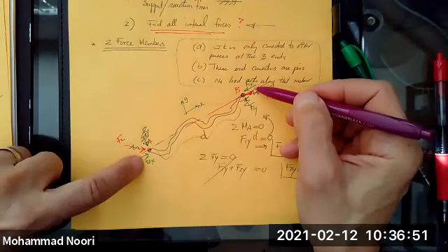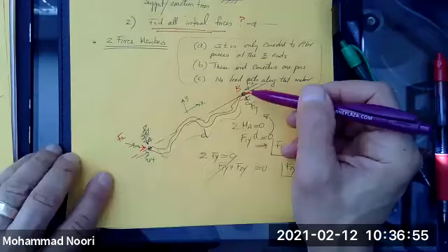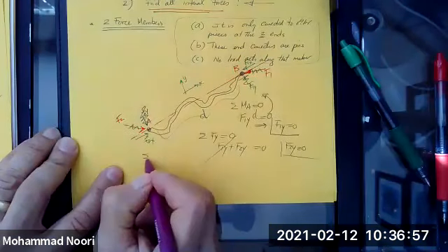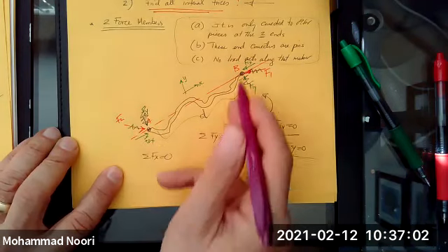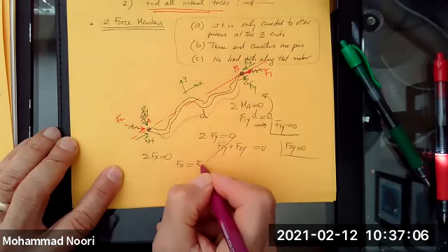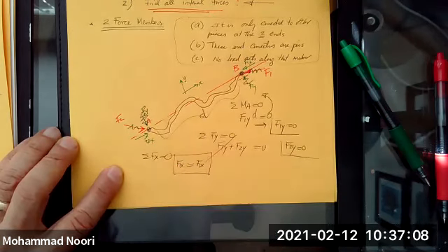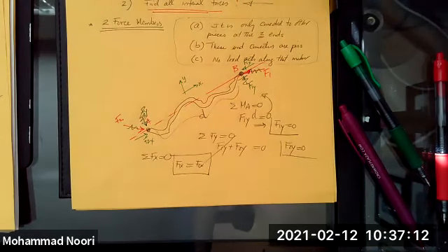And I can have only two forces acting along x. But wait a minute. If I write summation of force along x equal to 0, you can easily see that then F1x has to be equal to F2x. This is not just a conclusion, but the property, the inherent characteristics of a two-force member that we have proven.